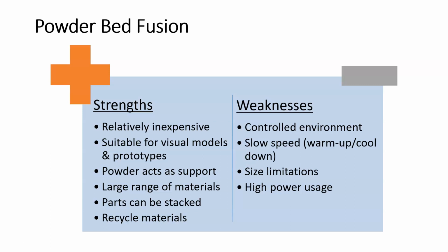But you also have powder particles. Whether it's plastic or metal, powder particles are very dangerous. They can be explosive. They're very bad to inhale. And so the whole build area is going to have to be controlled. The powder reservoirs and supplies are also controlled environments. That means that the machines have to be specially made, purpose-built for this.